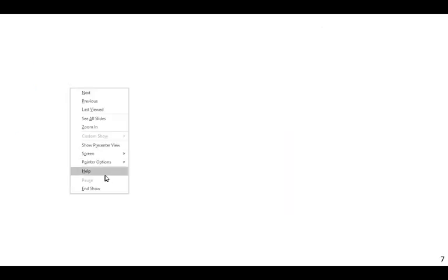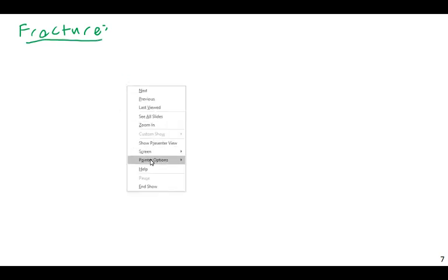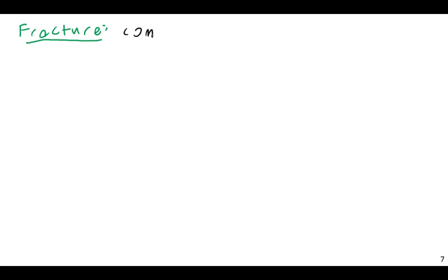Our next limit state for tension members, and we will actually look at these numerically, I just need to define and describe them first. The next one is fracture. Fracture is more critical than yielding because this is where something actually breaks. It combines fracture and yielding: you have to first stretch a surface to the point of yielding and then keep applying load until it actually fractures. So we say fracture, but it combines fracture with some yielding.